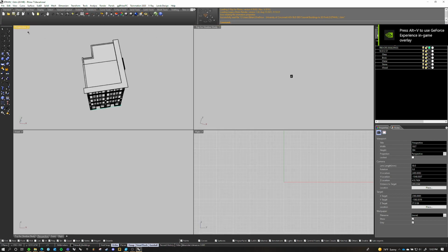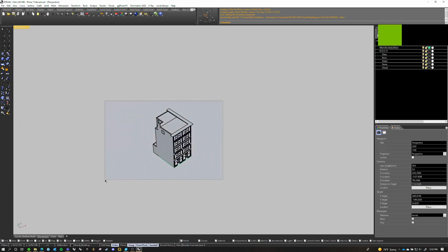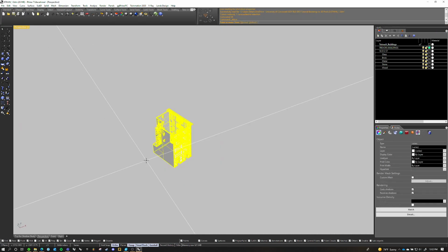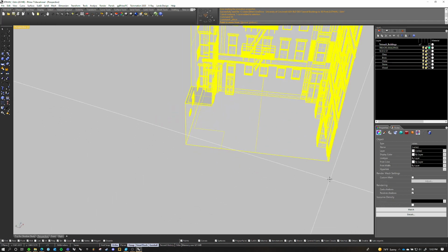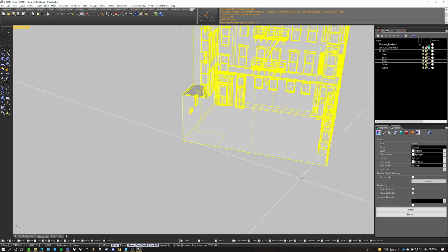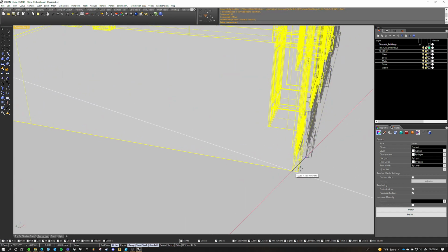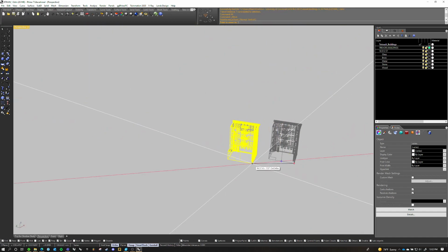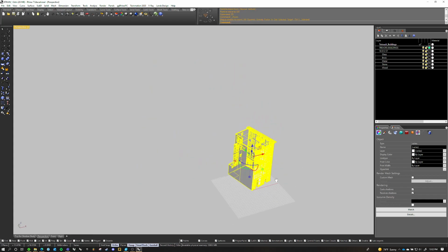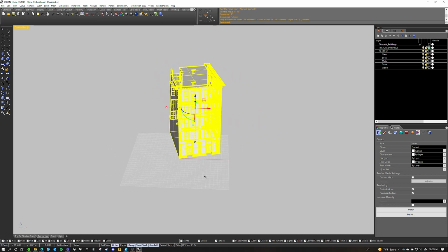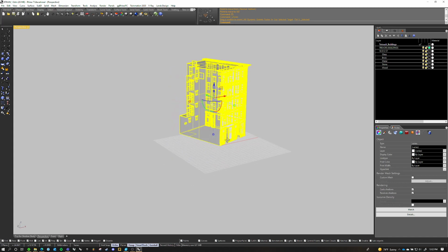So we're just gonna move the building. You can type in M to move and then choose a point. I'm gonna choose this point for the front and then type in 0,0 without clicking anything else and enter. And then that command that I showed you earlier, ZS enter. So we just moved the building to the origin point, and then oriented the camera back to the object.